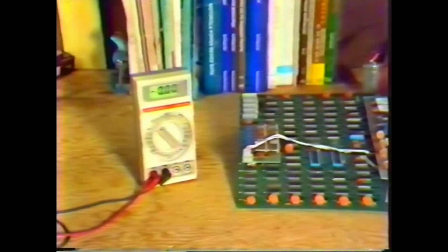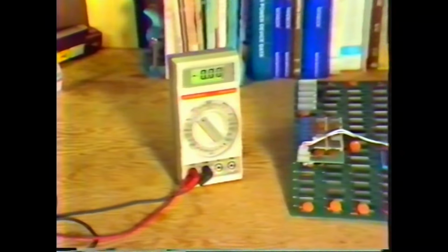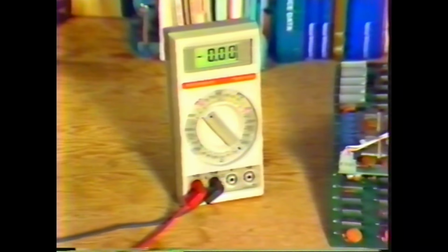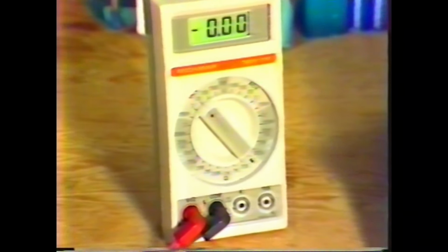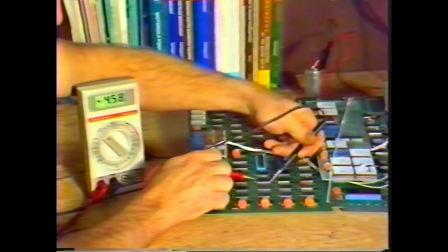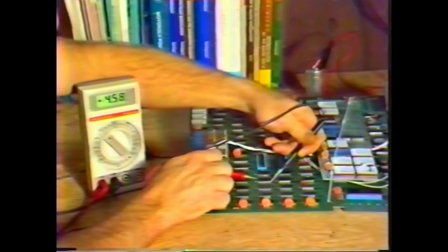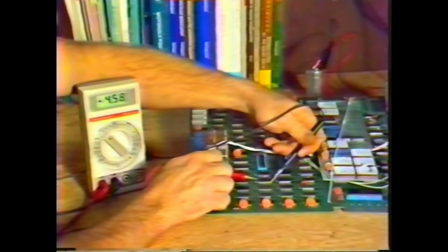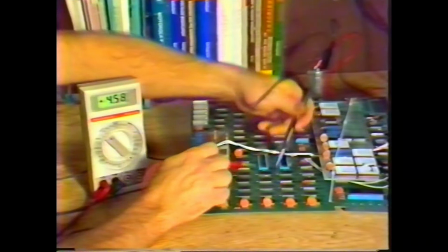When the capacitor fails, the power supply does not remain constant. That is, the voltage is constantly changing. When we measure the DC voltage of the power supply with our meter set on the 20 volt range, the supply reads 4.58 volts. That's because the meter averages the times when the voltage is up at 5 volts with the times that the voltage is allowed to drop lower due to the bad filter capacitor.